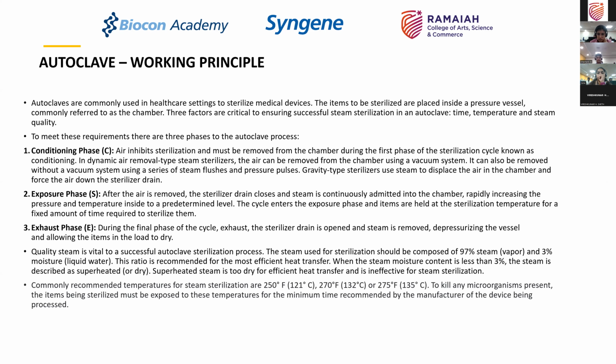Why will the air get displaced? Because the air, which is cold, will try to escape from the top or from the easiest path possible, while the steam will dwell in the system. Right. So air removal is very, very important, and generally in modern equipment you will see that a vacuum is used for removal of the air. So the conditioning phase is the first phase.